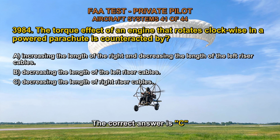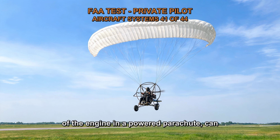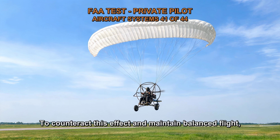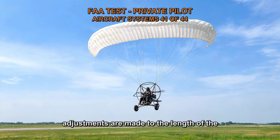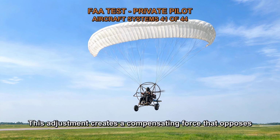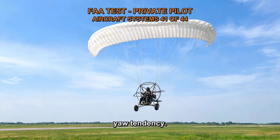The correct answer is C. The torque effect, resulting from the clockwise rotation of the engine in a powered parachute, can induce an unwanted yaw or rotation to the left. To counteract this effect and maintain balanced flight, adjustments are made to the length of the right riser cables. By decreasing the length of the right riser cables, the lift distribution between the wings can be modified. This adjustment creates a compensating force that opposes the torque effect, effectively reducing or eliminating the yaw tendency.